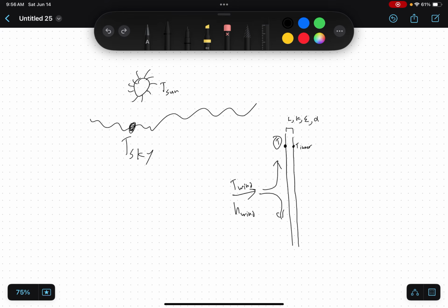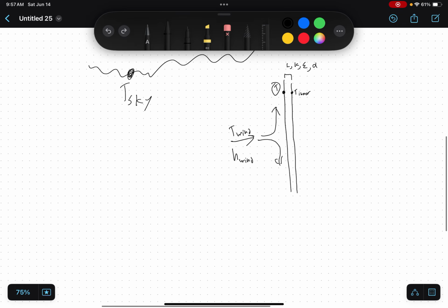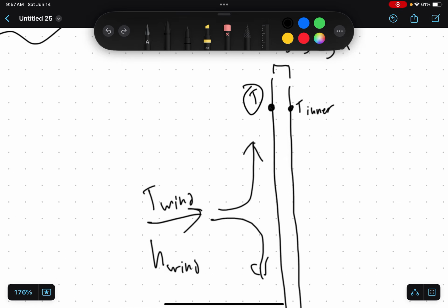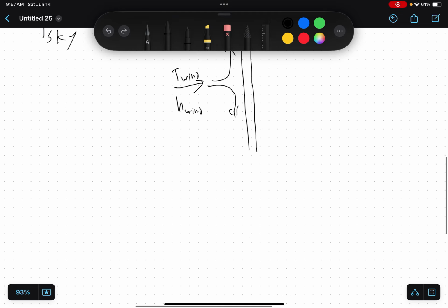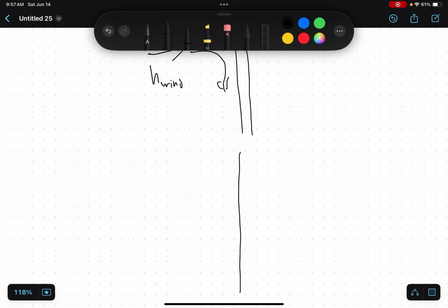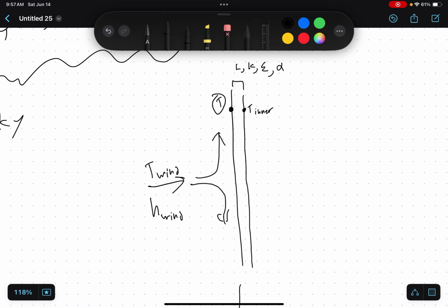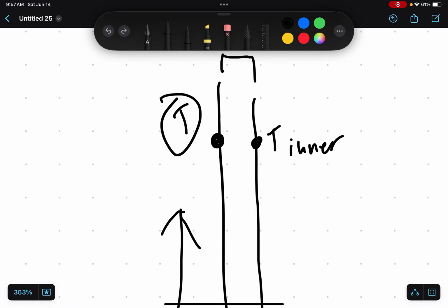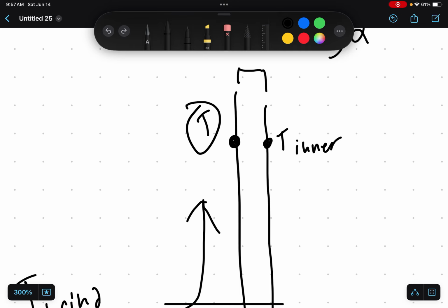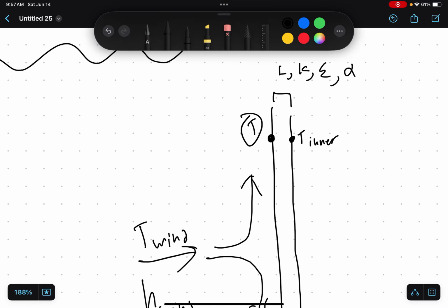So step one is the same step one that you use in any class, and it is to write out an energy balance. So I'm going to zoom in right here. So what do we have entering and leaving? Right there. So we talked about conduction. So that's heat going from the outside surface to the inside surface, assuming the outside surface is hotter, which I'm going to assume. Even if it's not, as long as you keep your sign convention consistent, it will return a negative number, and then you'll know what that means. But anyways,